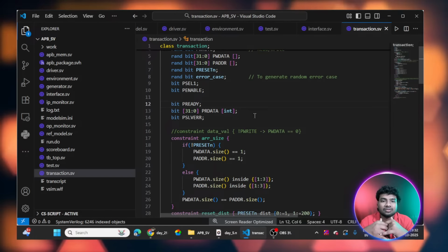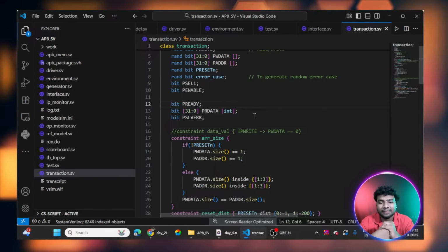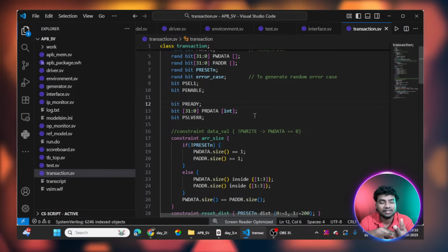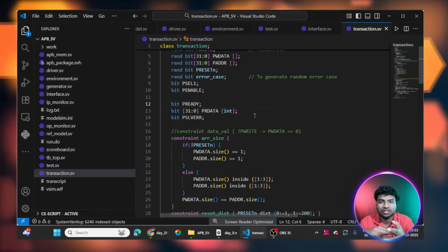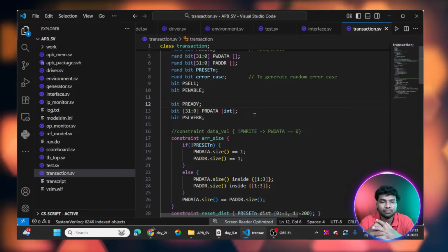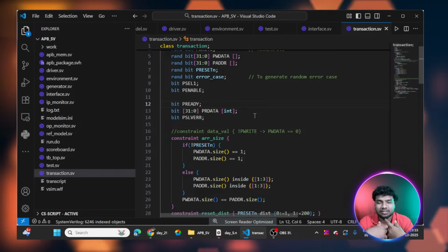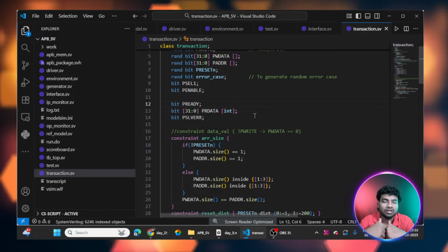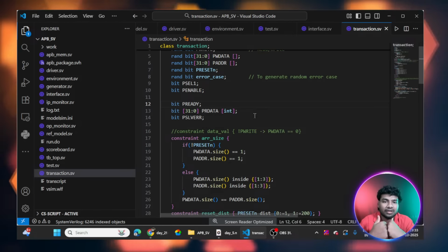If you want to avoid this kind of scenario, you have to practice every day and learn all the techniques. There are a lot of techniques for clock domain crossing synchronizers. One of the best techniques is to use a FIFO buffer. We already saw in our masterclass how to use a FIFO buffer for different clock domains and different baud rates in UART. It is very important. You can also use techniques like a toggle synchronizer and clock synchronizer. You can learn these techniques by experimenting, by writing and working with the code. That is how you can improve your coding skill.